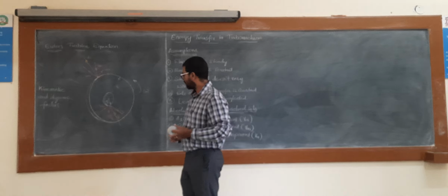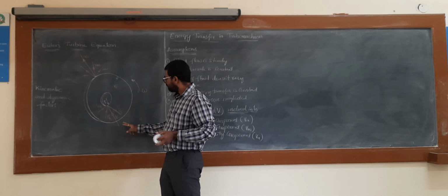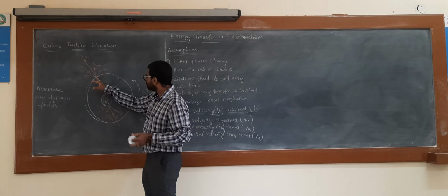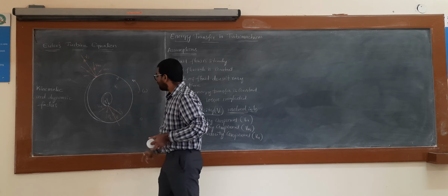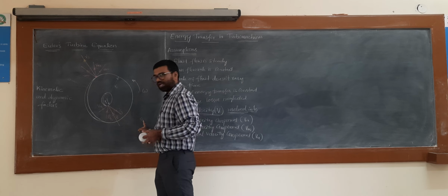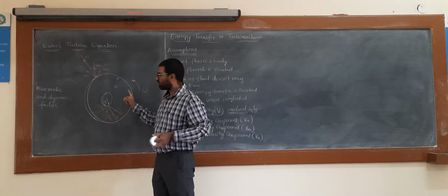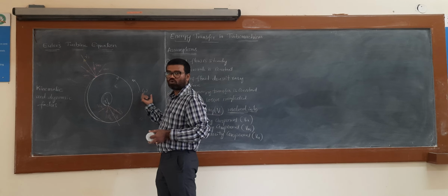See here the absolute velocity v1, which enters the rotor at inner radius r1 and leaves the rotor at outer radius r2. And the O1 is the axis of rotation of the rotor, and the rotor is revolving with the angular velocity of omega.